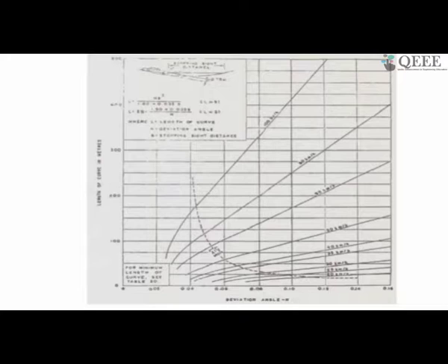So as I told you, if someone is traveling at a higher speed, the vehicle can be thrown off from the summit curve. So that is the major thing which is going to happen. And the other thing is that if it is not designed properly, particularly if it is not meeting the stopping sight distance, and there is any object lying on the other side, a stationary object, the vehicle may not be able to see it and get into an accident.